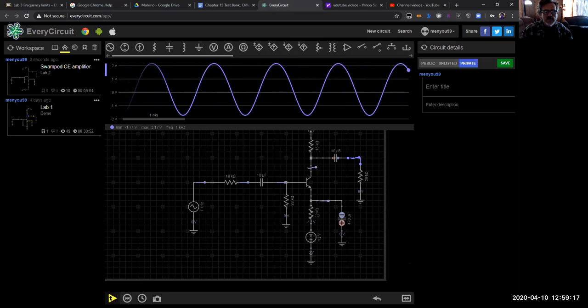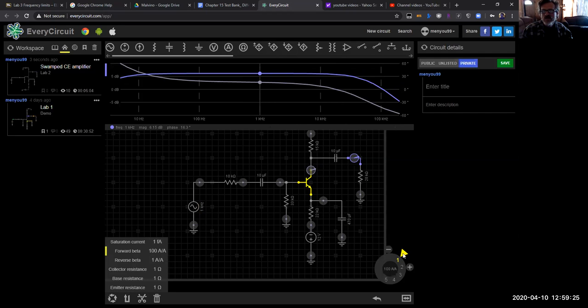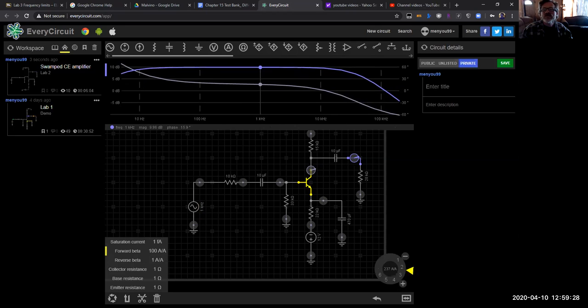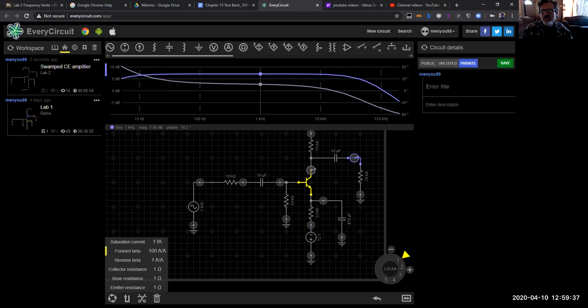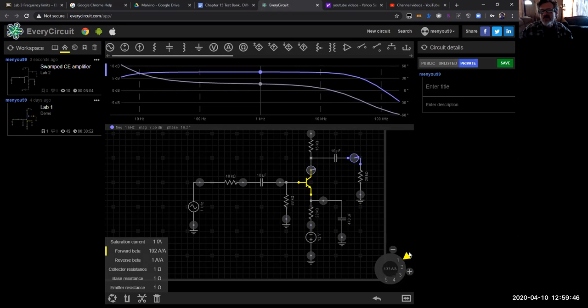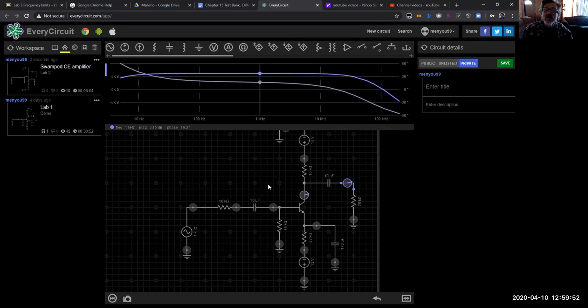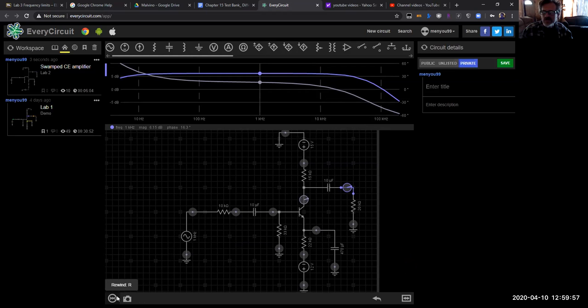As far as that, there we go. Seeing what your Bode plot is, you get your overall response, and even from that, changing the beta value, you can see it changes there. Notice it affects more the amplitude of it, right? But notice there is a slight frequency shift here. Not severe, but there is an effect overall. And that's what it is with this, just to get you familiar with how the RC time constants interact with the circuit. And I think this lab was fairly straightforward.